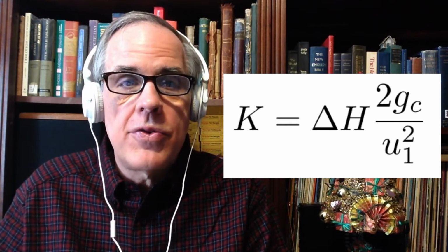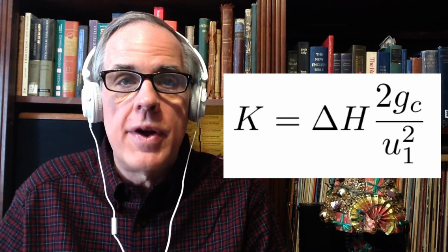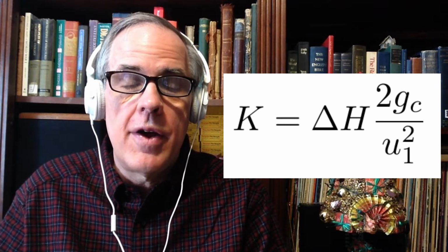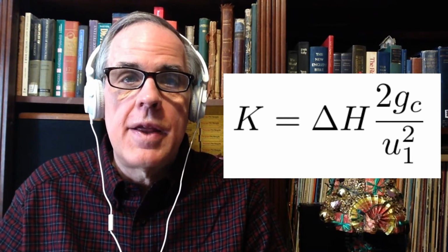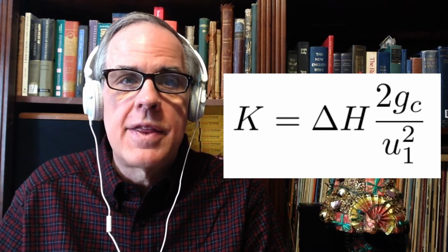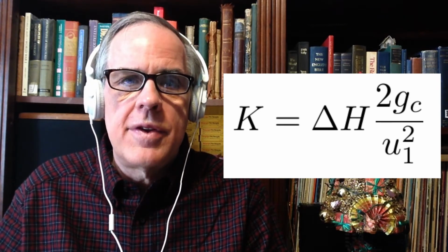The K values can be above 1, and very frequently are for high loss devices. In this experiment, I'd go through the math in some detail. I said that you could actually relate K values to discharge coefficients if you know that internal area. So, in any event, those are the K losses, and they're important.